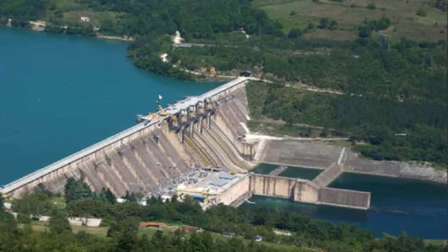The water level increases and water is flowing from the dam. If we do not provide this slope, then the water comes with heavy impact force, and it directly erodes the surface or land of this dam, and it also creates damage to the construction of the dam. For avoiding that, we provide the spillway.